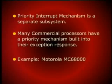However, different processors may use different priority mechanisms which might be built into the processor. As an example, the Motorola Series 68000 provides 7 levels of priority interrupts. The priority resolution is a part of the processor architecture. A separate chip may be available along with the CPU for resolution of the priority.